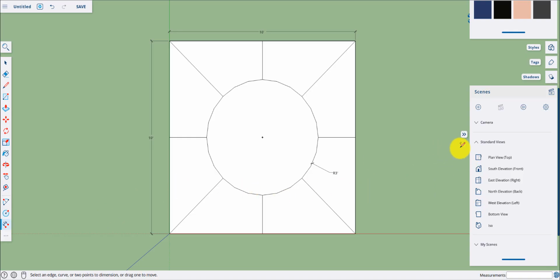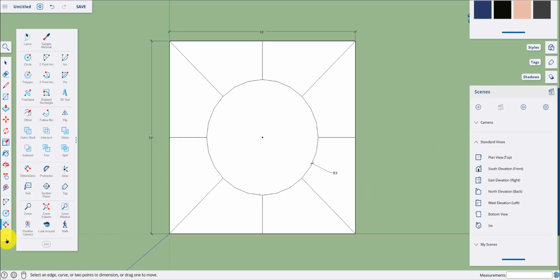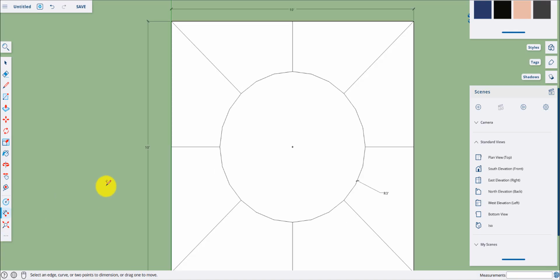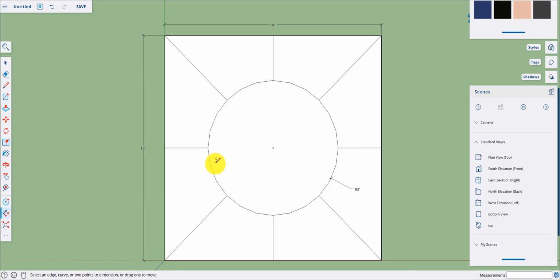So to get set to turn it in, you're going to go to your 3 dots, zoom extents, so it is as large as it possibly can be on your screen. You'll press save here, and then you will go to Google Classroom, and you will submit this whole file in Google Classroom and turn it in, and that will complete your first drawing.